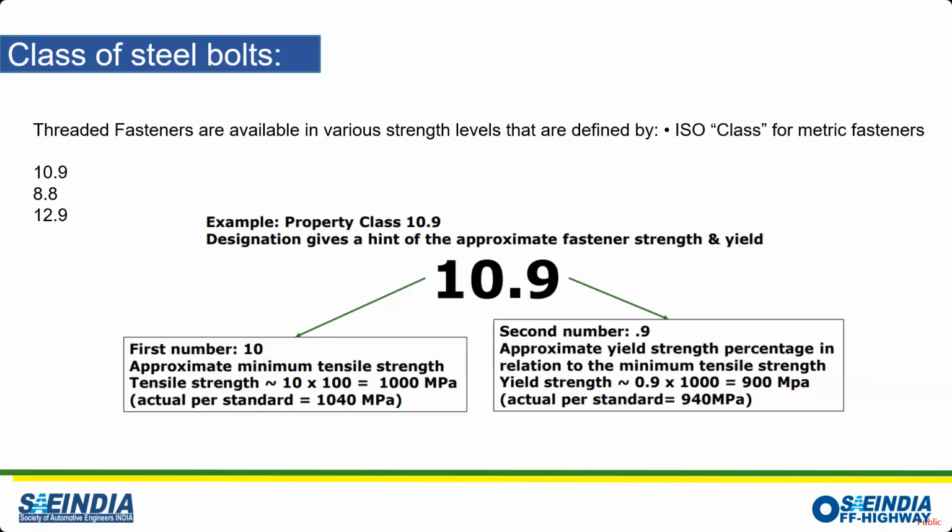So if you want to use a bolt with a higher clamp load capacity, you will be choosing the bolt with the higher grade. And you need to also select the equivalent quality of the nut for that bolt. So we'll see some calculation part in the subsequent slide.